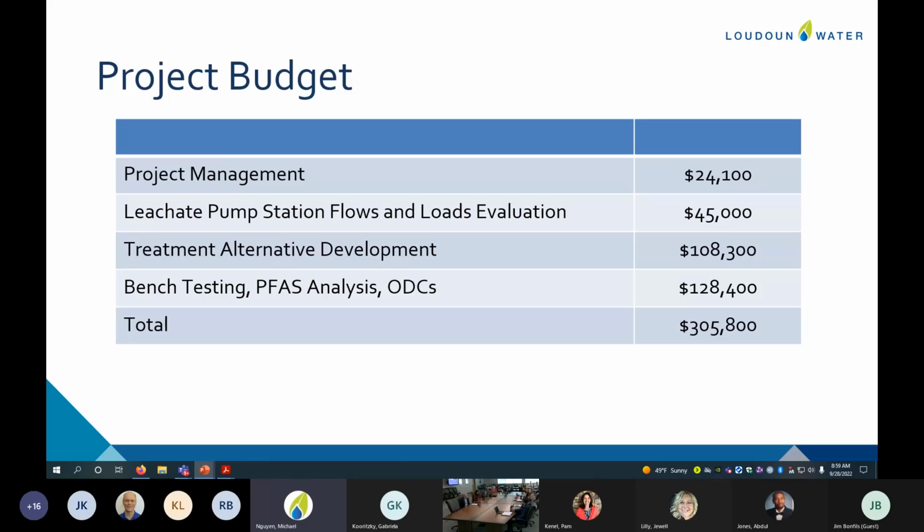Yep. So the treatment alternatives, when we start saying how big of a footprint we need for this process and how much it costs, are also sized by how much flow it has to treat. If that 7,000 gallons went to 14,000 gallons, it would be double the size and likely double the price. And we have to size it both for current flows and future flows. So we have to take that first step of knowing what our flow range could look like before we can get to capital costs and square footage.